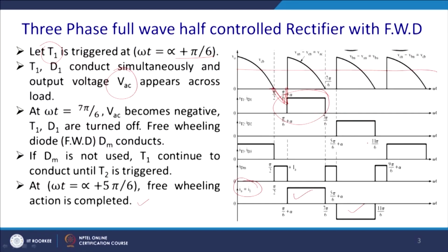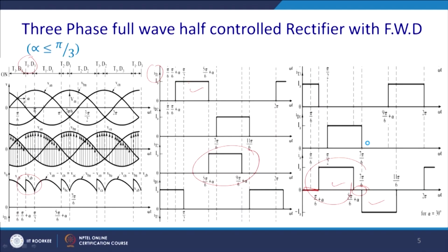Okay. So, we have to do the Fourier analysis of this waveform and ultimately work out what the harmonic content of it should be, what the THD of it is, and how we can mitigate it. Of course, we cannot use thyristors. If you use thyristors, we have to go for different solutions, but apart from that we need to revisit how to mitigate this problem.